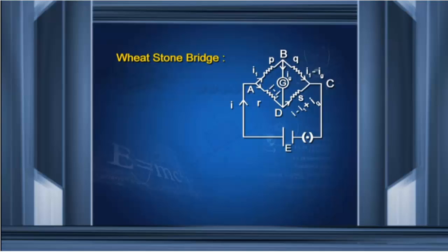If the current is flowing from high potential to low potential, then the potential difference is decreasing, so we take the potential difference to be negative. Whereas, if we are moving in a circuit from low point to high point, then we are moving in the increasing potential, so the potential difference is to be taken positive.